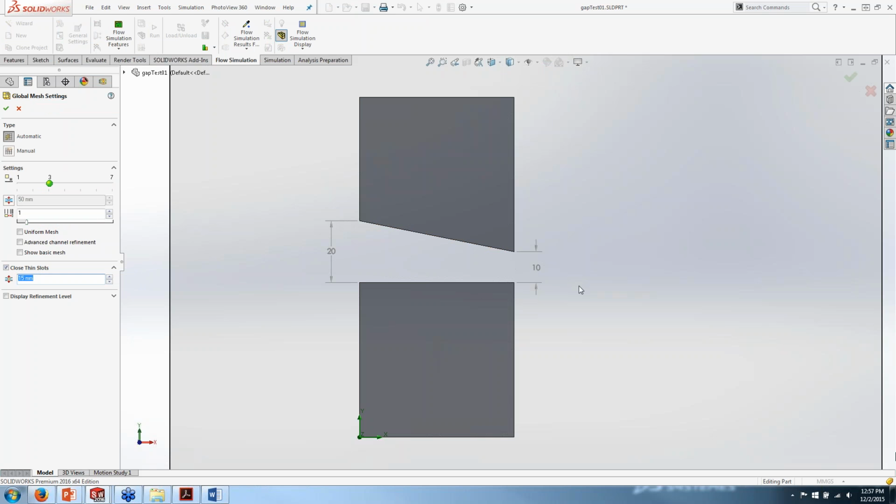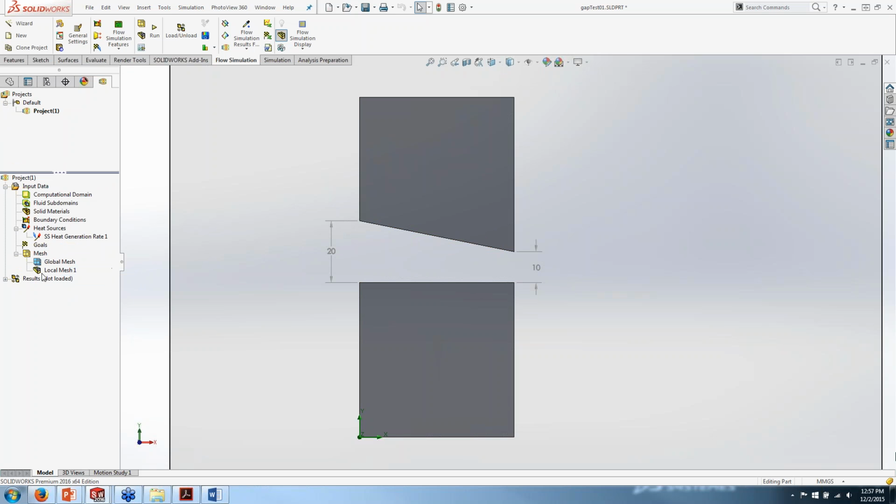And you see I have this gap here that ranges between 10 to 20 millimeters. So 15 millimeters actually corresponds with this point here, roughly. Okay, so it should close, theoretically, this region off right over here on this side of the model and leave this region open. Okay, and if I go ahead and mesh and run this thing, which I've already done, you can see what the results look like. You can see the region that gets closed off.